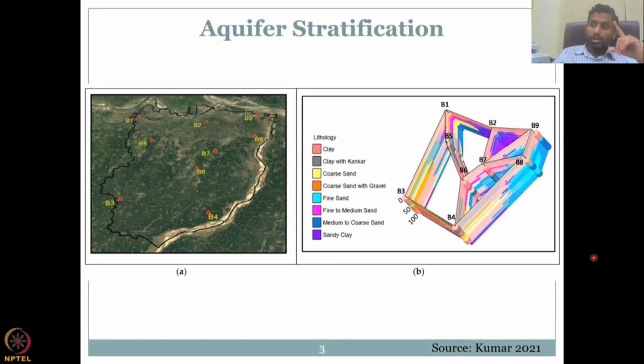It's good to have these colorings and as many layers as possible. When you do a model, there is no point having this many layers because of the computing power which is needed, and also most of these properties, if you remember from the porosity and hydraulic conductivity lectures, are in the same range. So they'll just club everything and make it 1, 2 or 3 dominant layers.